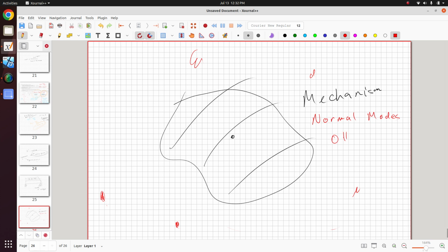We looked at the 0 Hertz natural frequencies. We looked at the mode shapes. And that was very useful. We use these mode shapes to identify where we have instability, where we need more support, or where we have soft stiffness in the model.